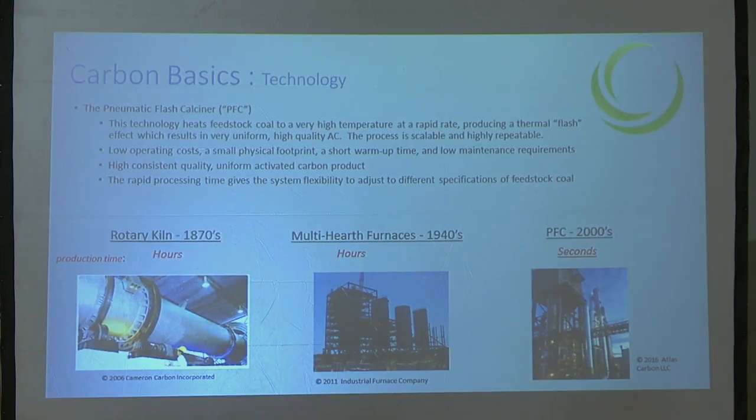It's called countercurrent flow. A similar type of process, the multi-hearth furnace, came about in the 1940s. These are big vertical heat stacks, basically. There are different levels of heat with big rotating arms that stir the feedstock. As the carbon drops down, it heats up a little more and vapors get driven off. Again, countercurrent flow. These processes take hours and hours of stirring, lots of mechanics.